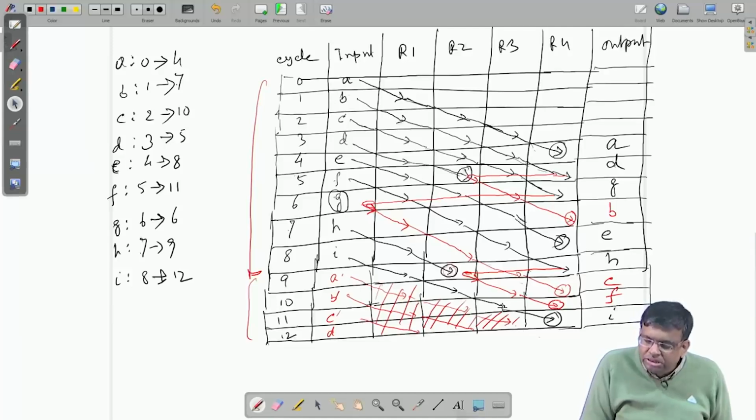Okay, that is 4 registers are good enough to store variables of this LS cycle and live variables from L plus 1s cycle, okay, in any system cycle. Like system cycle number 9, I have got H coming here, I have got G coming here, I have got F, but I have got also A prime, 4 are required.